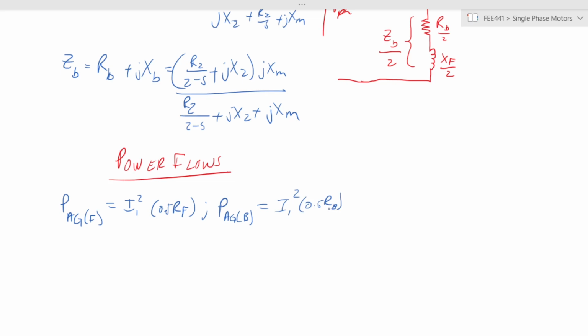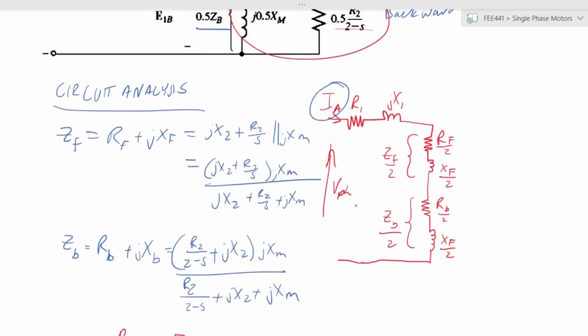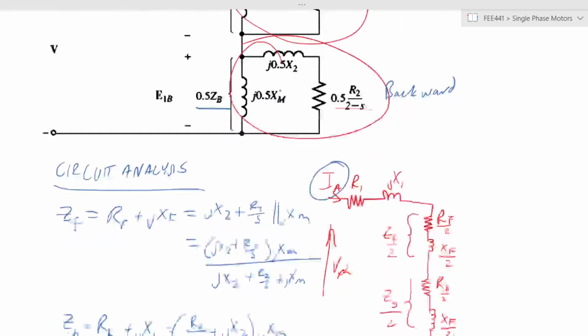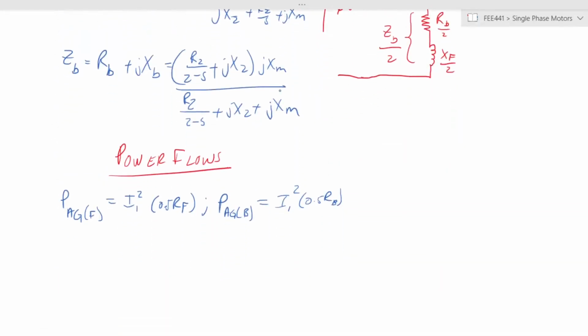RB. Now, likewise, if you know the resistances, for example here, the RF only has an R2 component. This R2 is the only resistive component in the entire impedance there. So you can make use of that fact by attributing it to this RB here. This is something that we made use of in the cut that we did for three-phase induction motors.